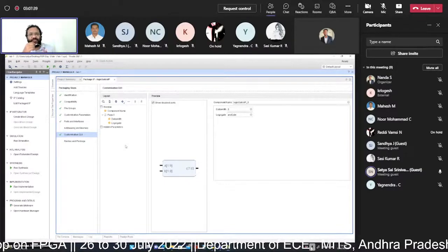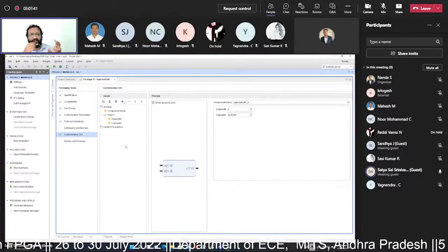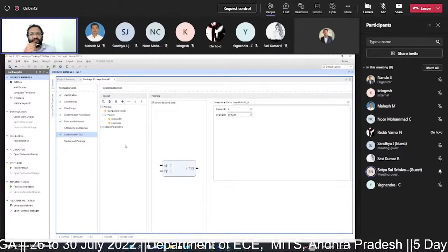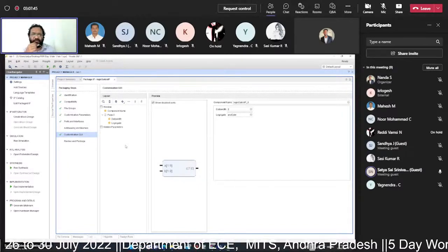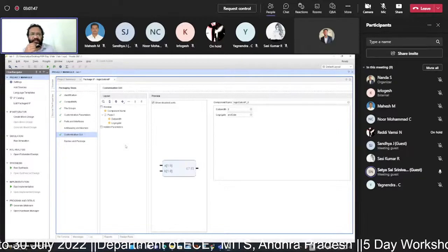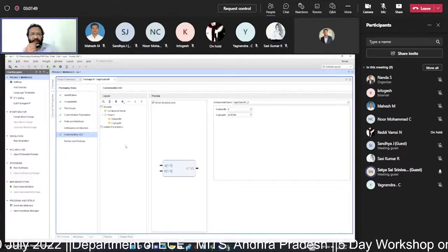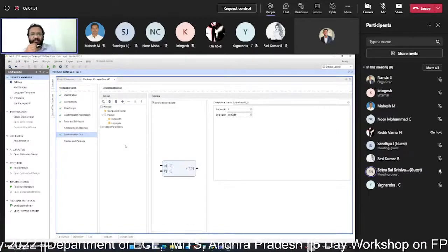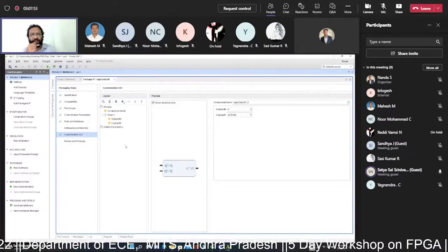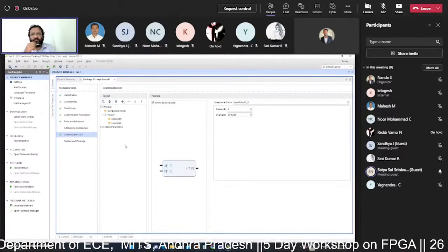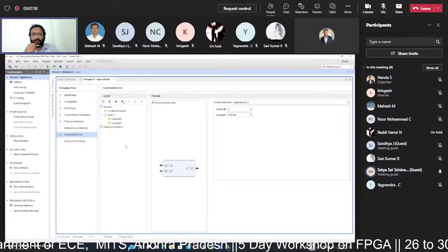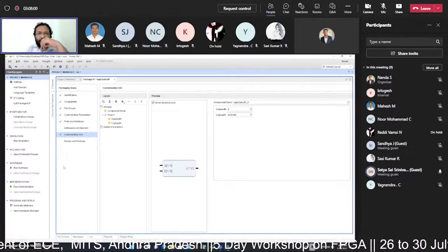In that window, on the left hand side you would have seen the IP block diagram, and on the right hand side the customization menu. Similarly, for our user design, we can check how our customization GUI is going to look after you package your IP. It is just showing you the layout.